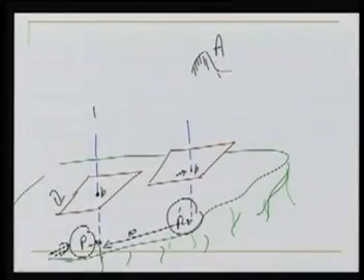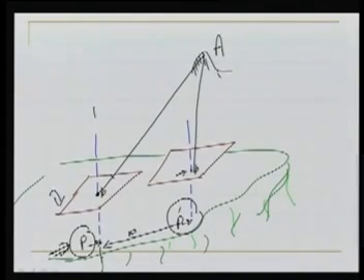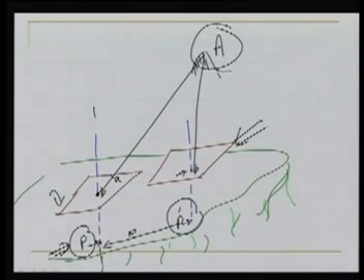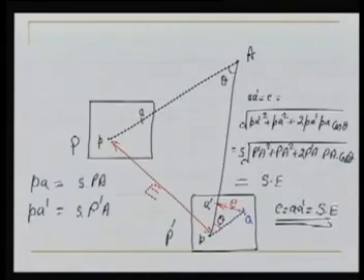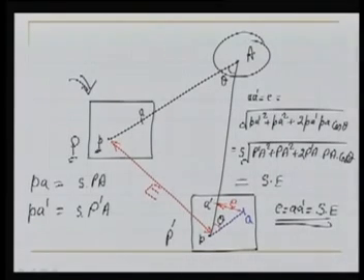Now what is the effect of this? What we are doing here, we are plotting the points. In this case, a point A will be plotted here, while if the table is miscentered, the same point A will be plotted at a location A dash. Let us look at the same thing. Over here, this is the first position. There is no miscentering error in this case. Small p is above capital P, and this is where this A is being plotted.